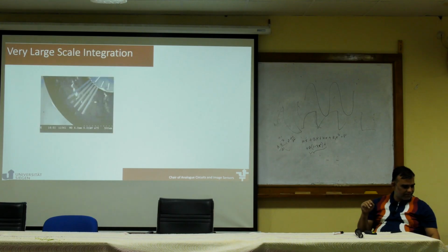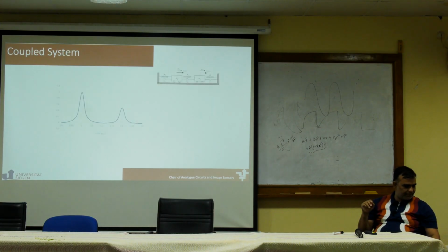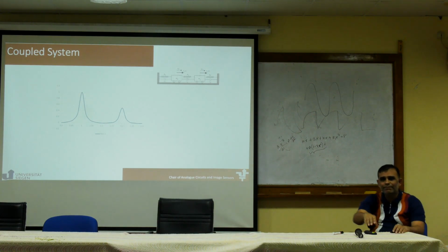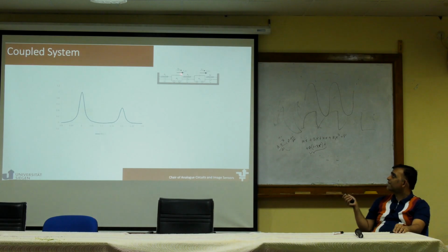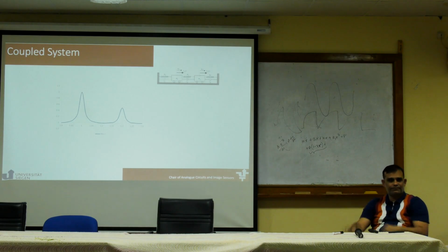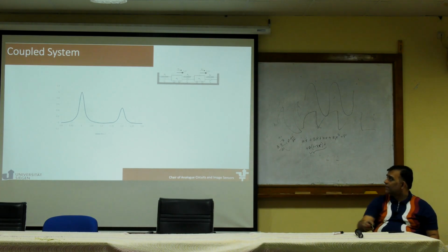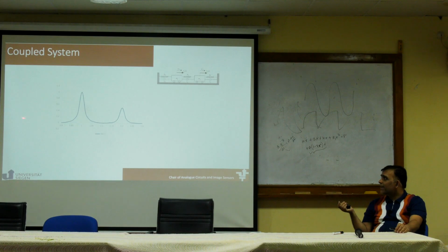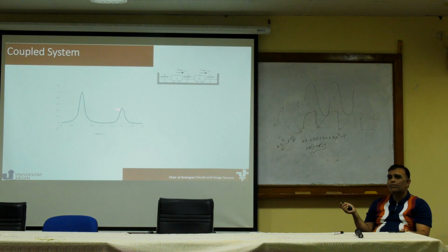Think again, two pendulums. Actually, you know what? Do I have a theory of two pendulums? Yeah, I've got two pendulums here. So, these are two mass spring systems, and I have coupled them with another spring. So, in the end, what will they do? They will either go like this or they will move together. If you now look at their frequency plot, we will have two resonance frequencies, one in which they are moving in plane, together, and one in which they are moving out of plane.